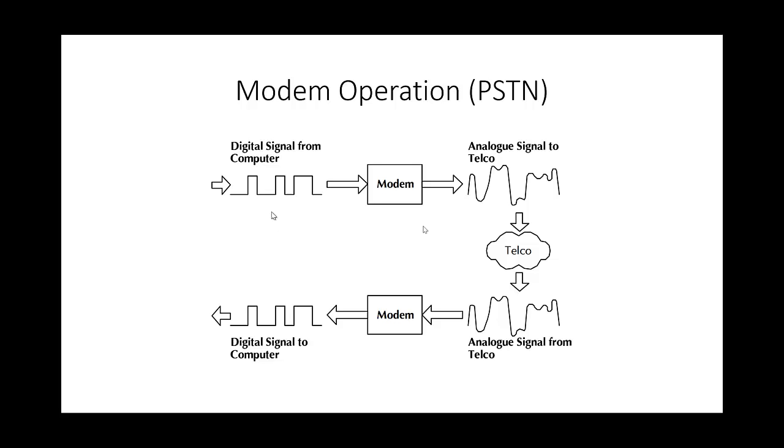In order to transfer digital data across a PSTN system, it is necessary to use an analog, voice-like signal capable of propagating without distortion along the line. This carrier signal is modulated to encode it with the digital data from the sender. At the other end, the signal must be demodulated to extract the digital data. This process is carried out at each end by a modem, as shown on the screen. PSTN links offer on-demand connections over circuit-switched networks.